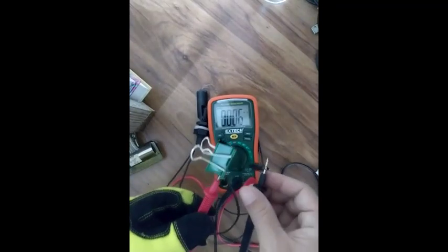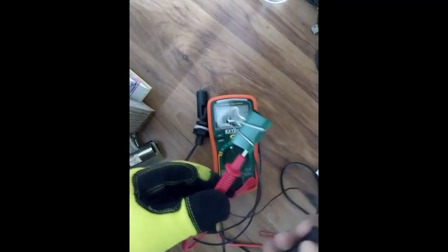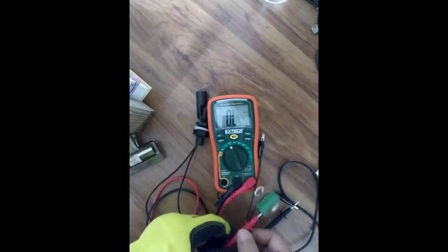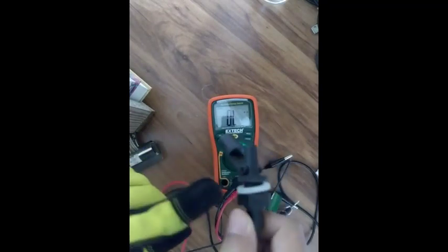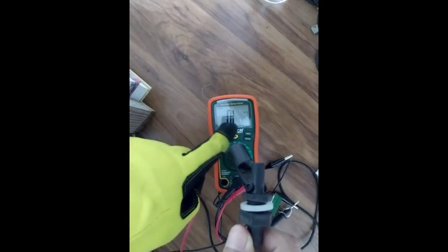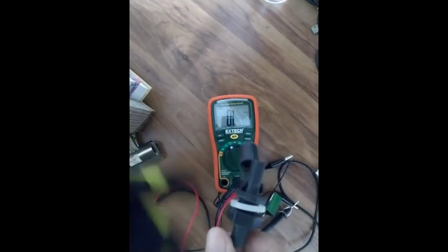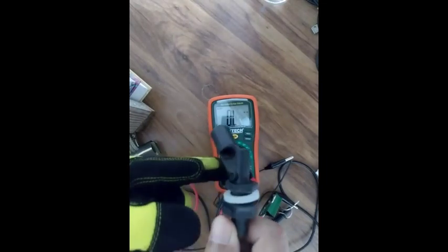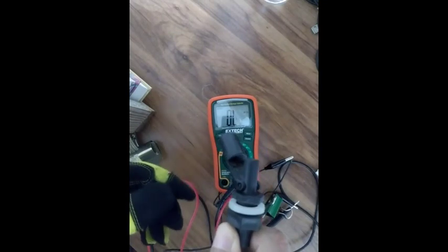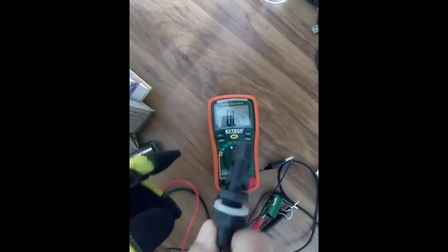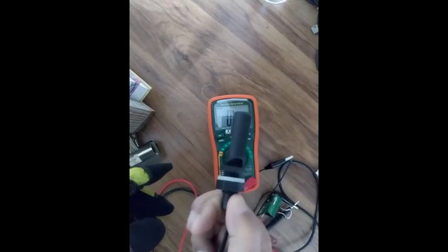So now I have both terminals of the level sensor connected to the multimeter, so now I can check. For example, right now the contact is open, and therefore it's reading open loop resistance, or infinite resistance. If I close the contact, you read 0. Open the contact, open loop. Now remember again, the float only pivots within the hinge. So I can install this like this or like this.